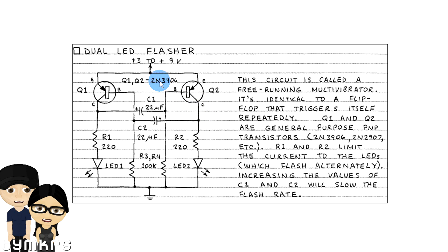So let's go through that one more time. We have the voltage source. When we turn it on, the base voltage of both of these transistors will be probably near zero, which means that this transistor is turned on. When this transistor is turned on, current will go from the emitter to the collector, and the LEDs will obviously be lit since there's current going through. But as the current goes down here, it also helps to charge these capacitors.